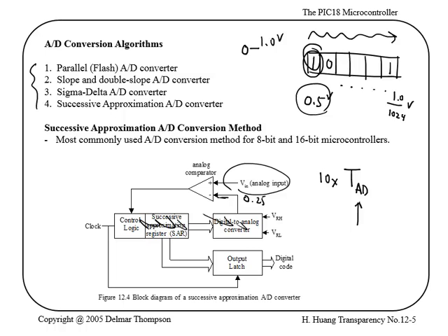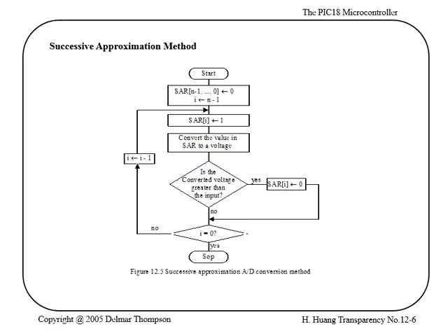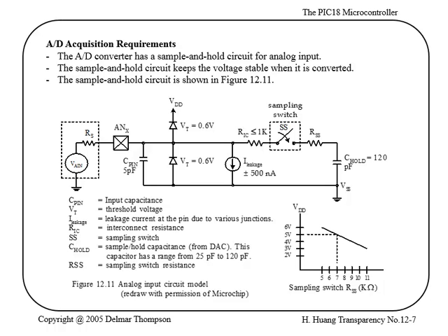So it's going to take 12 TATs to do a 10-bit conversion. And I'll talk about that 13 TAT thing later. So this is the algorithm, and this is what you're going to find in a PIC device. And I liked this. This is from PIC 18. This is PIC 18 specific. This is from the PIC 18 manual.